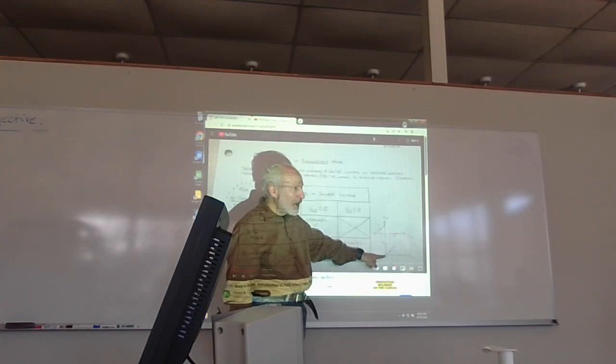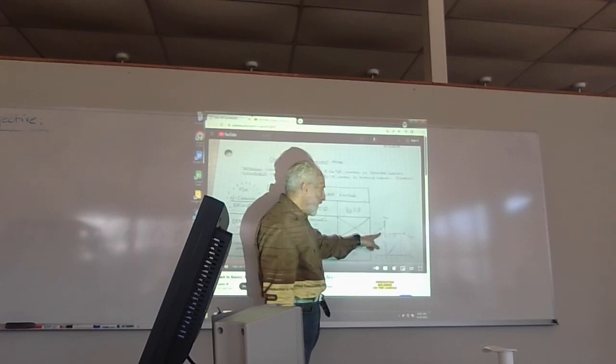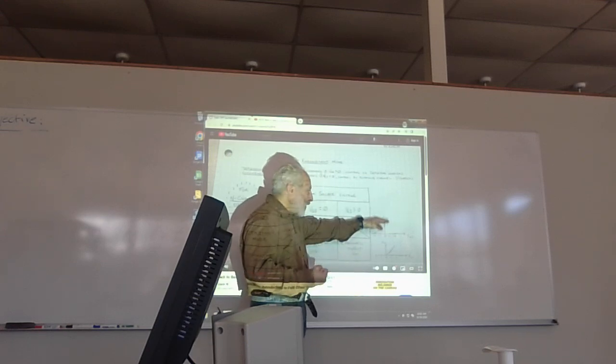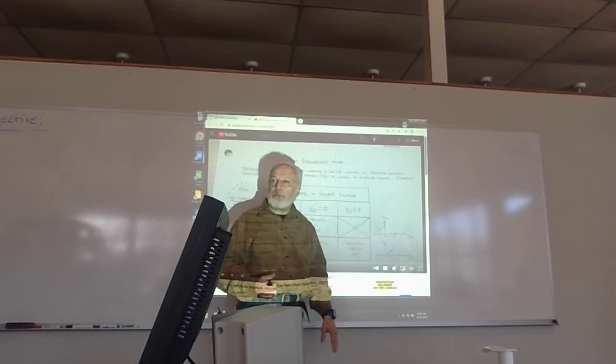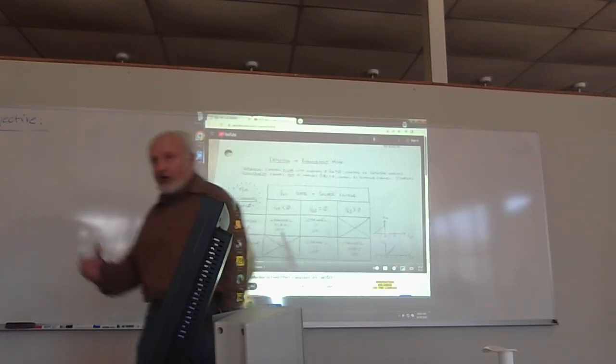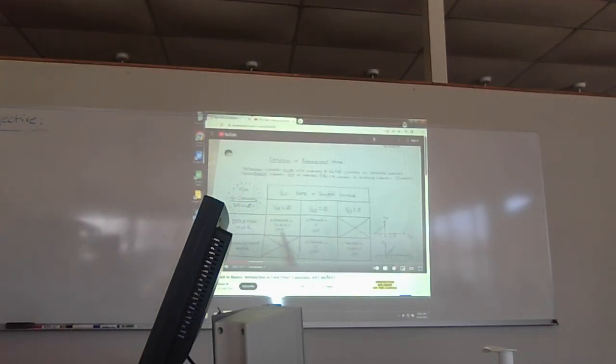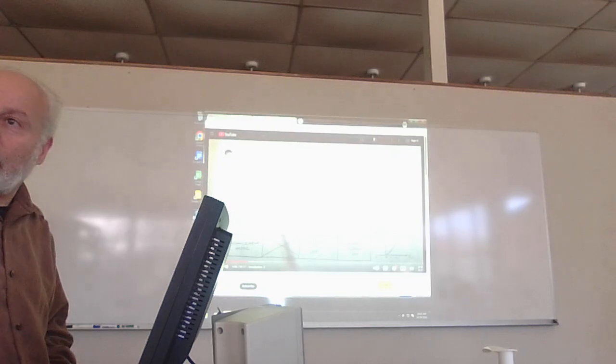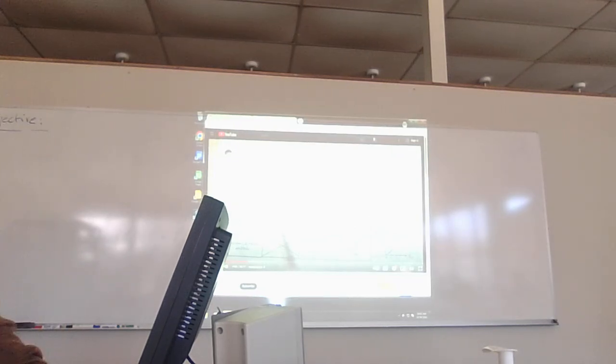You started out with no carriers and then you keep going from there. Here it goes backwards. The more negative voltage you have at the gate, the less current you have between the drain and the source. Once you understand these two, you're good to go. Got it? Okay? You said the more negative. More negative voltage you have for the depletion, the less current you have between what? The drain and the source, or ID, the current through the device. Okay? Right? We'll get to see that.